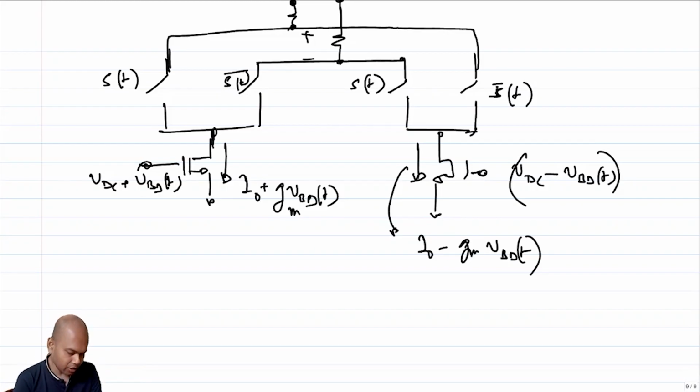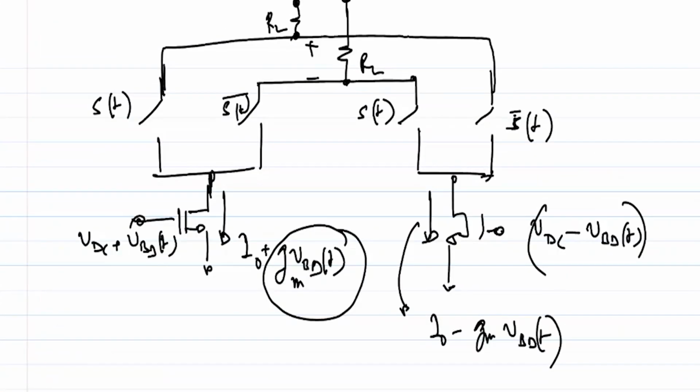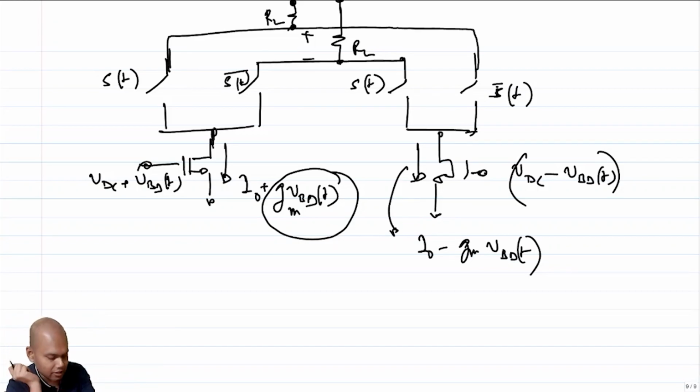Now, how do you get a gain? You get a gain because the current that you are pushing in is GM times VBBT, and if the load here is some ZL whose real part is RL, then the gain that you are getting is GM times RL times VBBT, and then the conversion gain, that is because you have times basically the C1, right? C1 as in the fundamental component of the switch, right? So that essentially is the difference between a passive mixer and an active mixer.